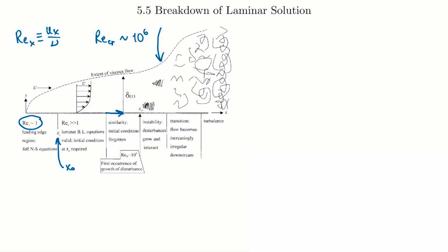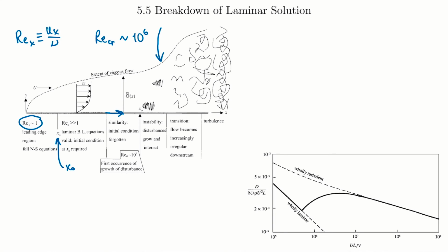In contrast, the wall shear stress for the laminar boundary layer varies as tau naught proportional to u to the 1.5 exponent. And this increase in resistance is due to the greater macroscopic mixing that's present in a turbulent flow. Now, this, of course, is also going to result in a different drag force, which ultimately is really what we're concerned about when we talk about boundary layers. And this variation of the drag coefficient can be expressed as a function of the Reynolds number. So I've got this other plot shown here, so we can see how this changes. Drag coefficient plotted against our Reynolds number. So we've got the laminar one down here, and what we'll call this transitional zone here. That applies if the boundary layer is laminar and then turbulent over the remaining part.